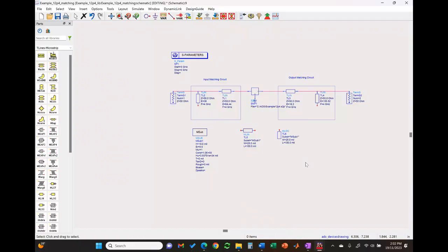You define the name of the substrate, the width and the length, and the same story if you have an open circuit transmission line. I will not do this over here, but in the midterm exam, some students, in some problems, did not use the microstrip line, but used the transmission line instead for some questions. So just be careful about this.